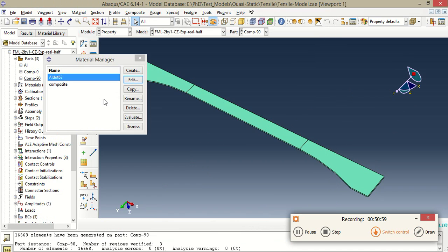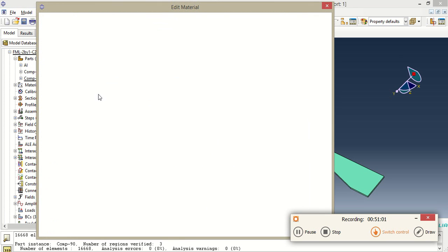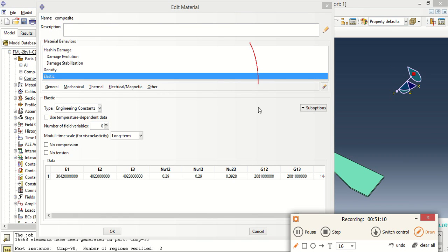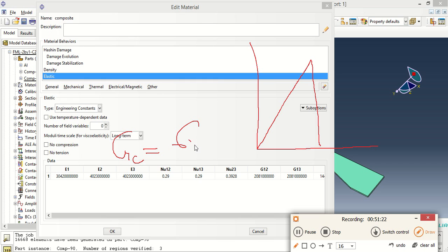So for the case of composites, similarly, composites are much more suited to that formula that I have given, because the composite curve is, ironically, just like a triangle. So your GC equals sigma y naught multiplied by fracture strain and multiplied by characteristic length divided by 2, which will be quite justified at this point, because the fibers and the composite as a whole, considered as a brittle material, feel like that.